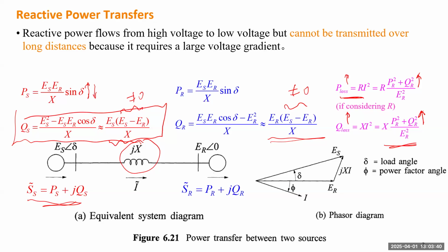For even higher, like an actual high voltage transmission line, they expect the variation to be very small. Okay, not as small as frequency deviation, but it's still very small. Let's say 5%. For a distribution system, that 5% may increase to 8% or even 10% in some areas, but it's still pretty small. So this gap at the most will give you about 5 to 10%